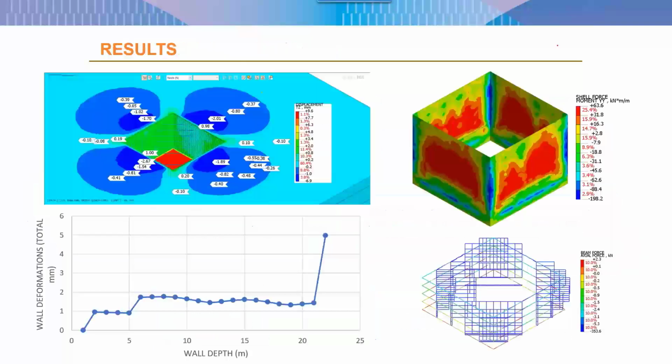So in terms of results, what do we see? Here our goal was to create the excavation, check for the excavation deformation along with the impact assessment of local areas. One of the ways of doing that is by checking along the trend line what is the extent of deformation as you move far away from the excavation.